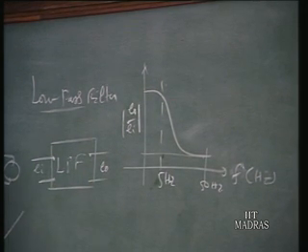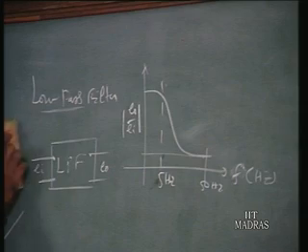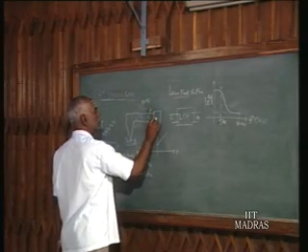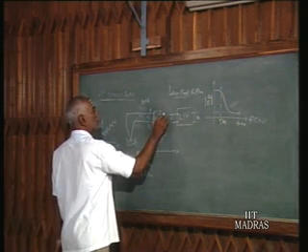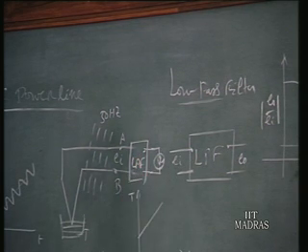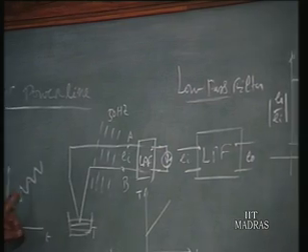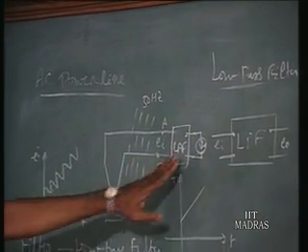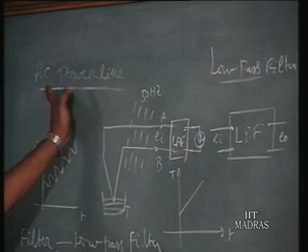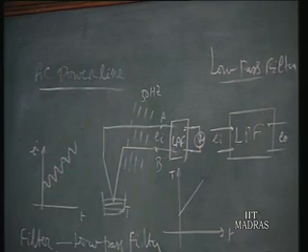So now, between the voltmeter and the thermocouple terminal, instead of connecting to the voltmeter directly, interpose this low pass filter, and then connect it to the voltmeter. So you have the reading. That is how the AC power line effect, the superimposition of the 50 hertz, is eliminated, and then we see the correct reading. That is, the error due to the nearby AC power line is eliminated by using a low pass filter.